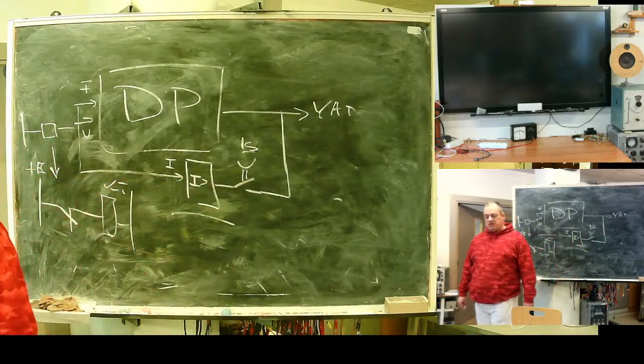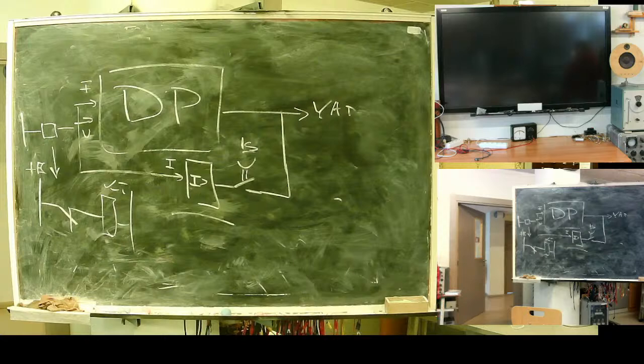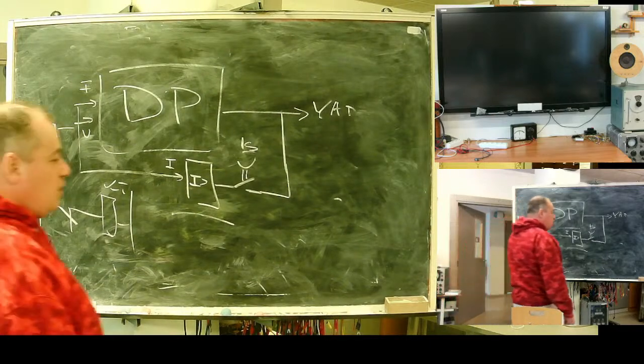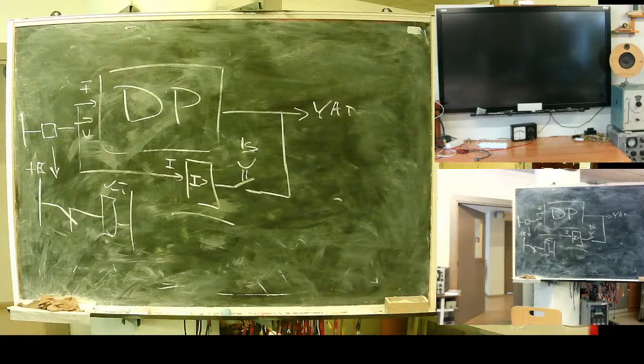When switch is on, relay is de-energized, but the circuit for instant protection remains active for 1 second. It's a mandatory thing. Non-selective instant protection should protect only 10% of line, 0 kilometer.